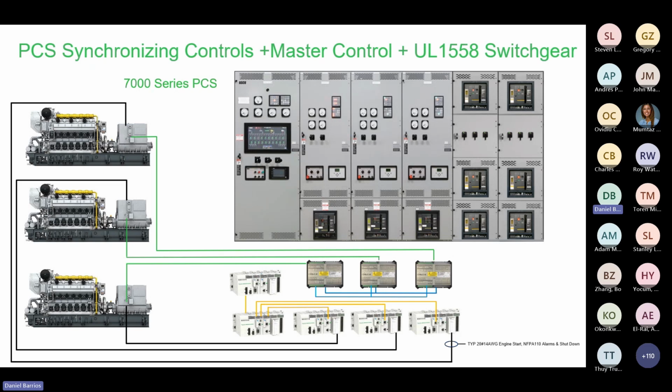Should you lose both of your master PLCs, the generators will start and your priority one loads will be able to transfer to emergency. However, since you've lost your logic beyond that, you do not have control to be able to release your priority 2, 3, or 4 loads, sort of to say. We can give you that in a sequence of operation. We can describe that to you better, and we can go through that.